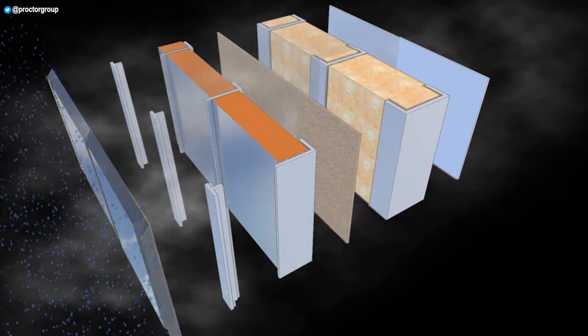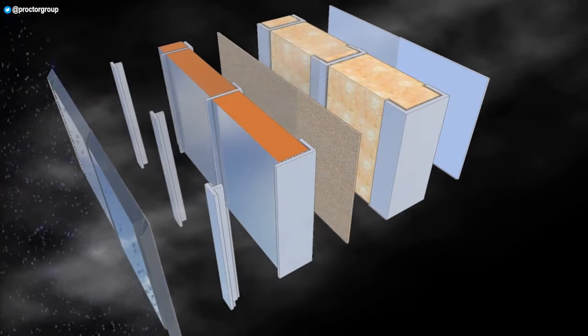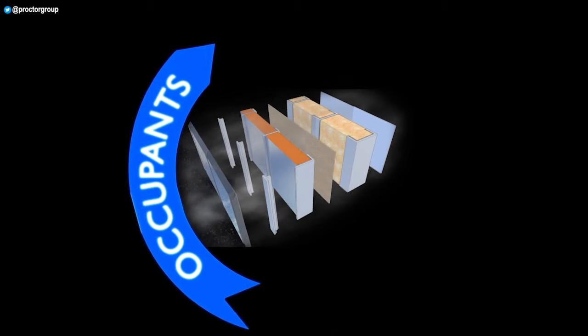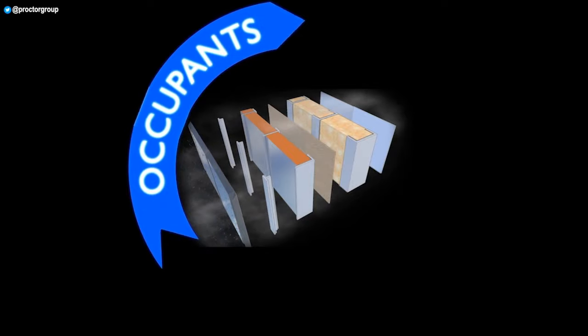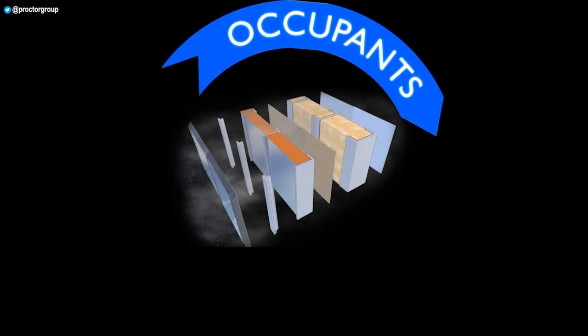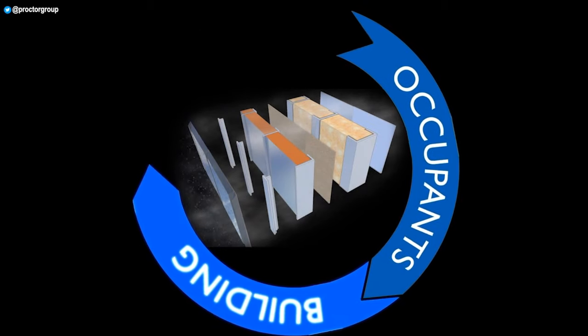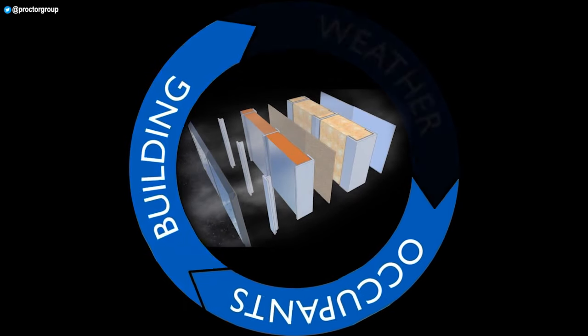In order to avoid the occurrence of excessive condensation, which can result in mould growth and damage to the building fabric and/or contents, designers should assess the amount of water vapour likely to be generated within the building and determine the resultant increase in internal vapour pressure above that of external air. They should then consider the physical properties of the construction, separating inside from outside, and how this interacts with the various moisture sources present.